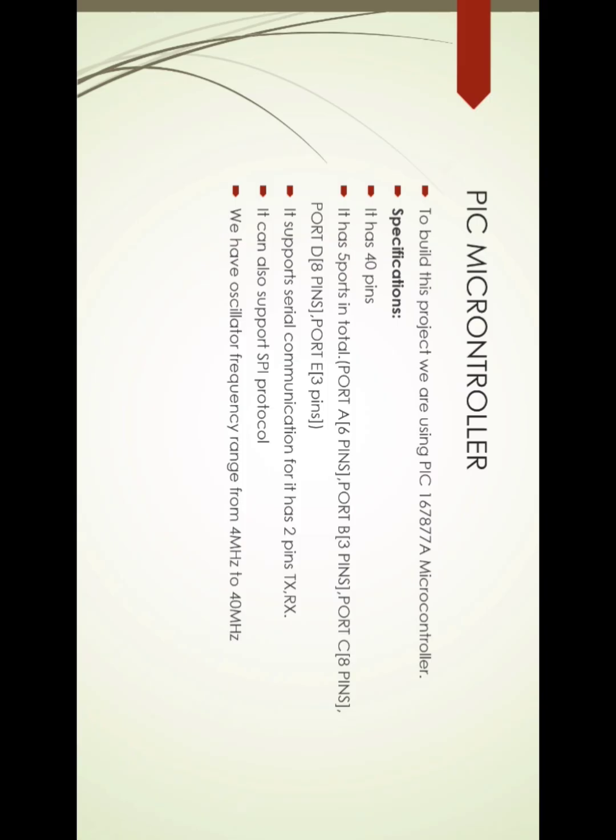This PIC microcontroller has 40 pins and 5 ports in total: port A, port B, port C, port D, and lastly port E. Port A contains 6 pins and port B contains 3 pins. Port C contains 8 pins. Port D contains 8 pins. And lastly port E contains 3 pins.